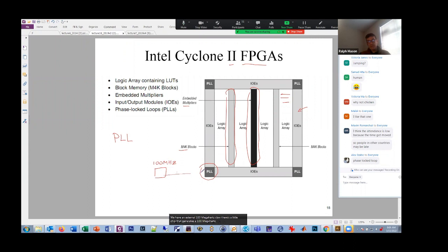And basically it comes into this divider block to the PLL, and the PLL generates, I think we've been using either a 5 megahertz or 10 megahertz, right? So it's the first block. PLLs are kind of cool. You can make divided down clocks and you can feed it around the chip. You can also multiply the clock up. So you can generate a 200 megahertz clock with that, increase the frequency.